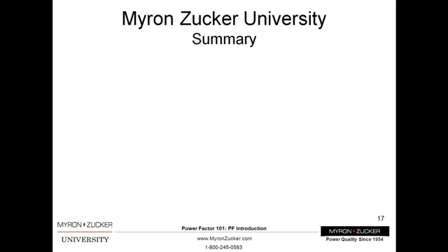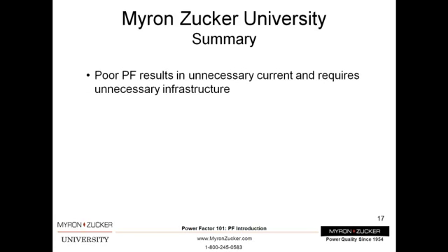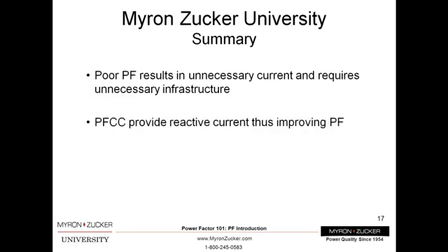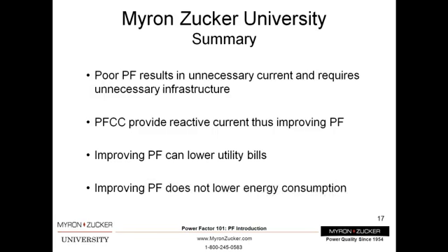To recap this training module, poor power factor results in unnecessary line current requiring additional unnecessary infrastructure. Power factor correction capacitors provide reactive current, thus reducing line current and improving power factor. Reducing utility bills is the number one reason for improving power factor. Improving power factor does not reduce energy consumption significantly.